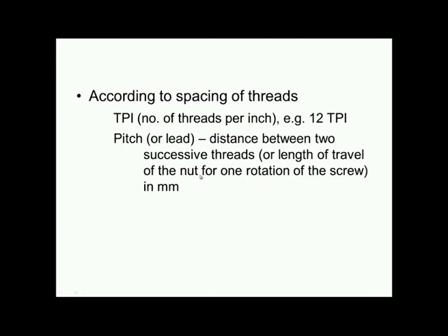According to the spacing of threads, I can say TPI, the number of threads per inch, whether it is 6 TPI or 12 TPI, like that we can classify, and depending upon the pitch also we can classify. So, pitch, or lead, is the distance between two successive threads or length of travel of nut for one rotation of screw. So, pitch can be 1 millimeter pitch or 2 millimeter pitch or 3 millimeter, like that.